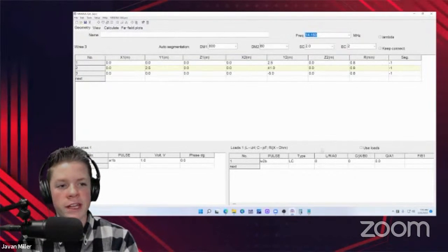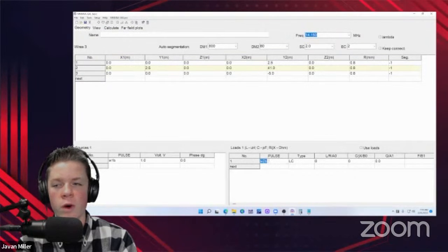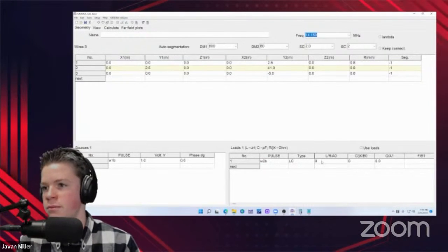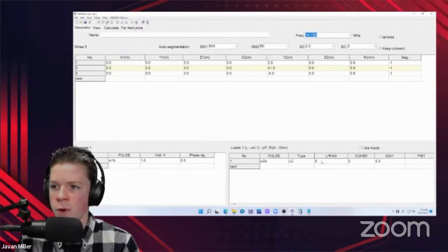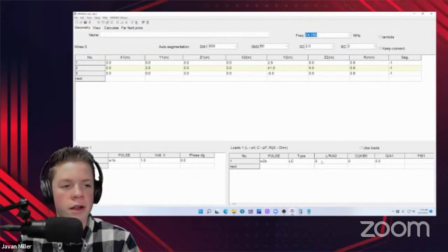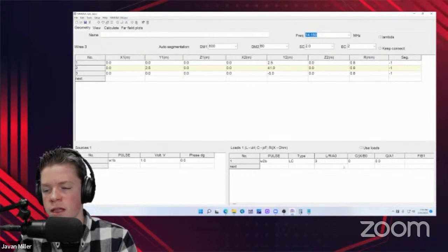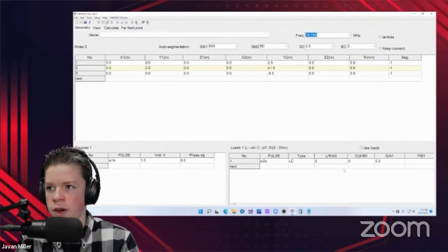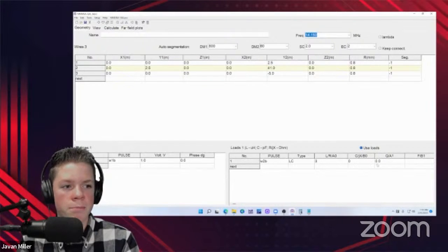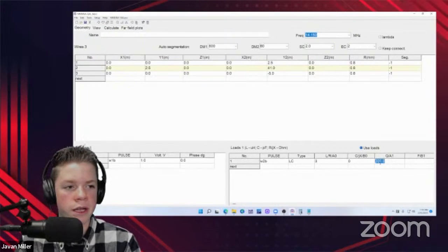So over here I added a load. This is wire number 2, at the beginning, and then I can enter, I don't know, maybe 3 ohms, or sorry, 3 microhenries for the inductor. I'm not sure exactly what it'd be, but we can just try and see, and we can optimize later on. And then right here is the Q. I guess we could do a Q of 200.